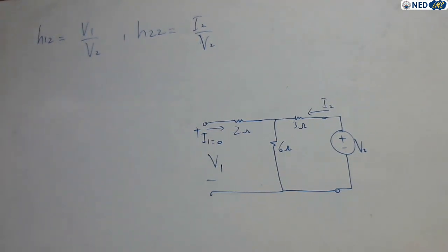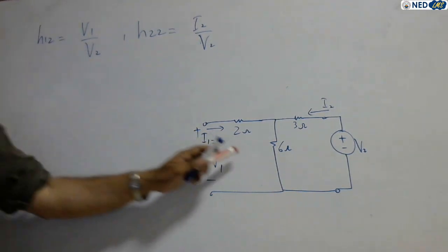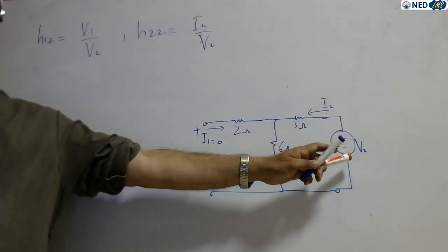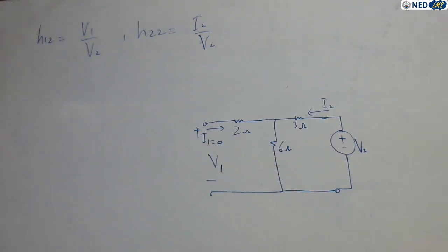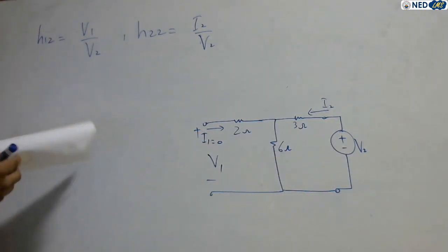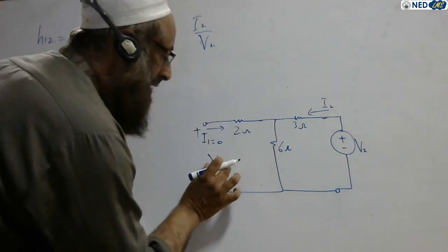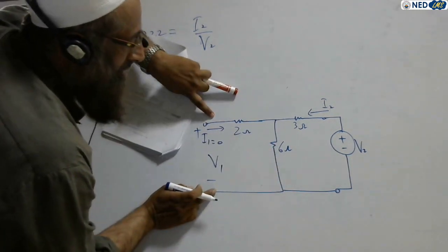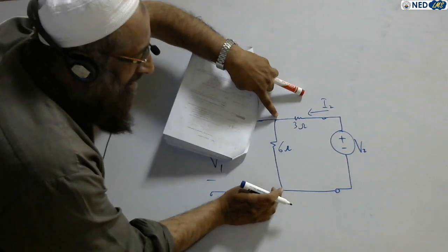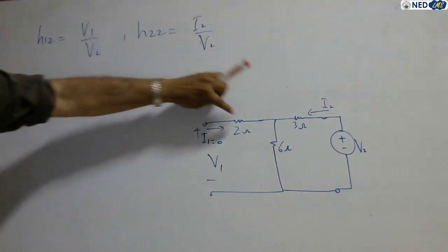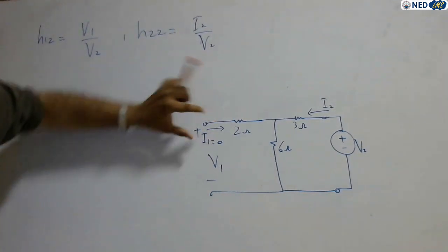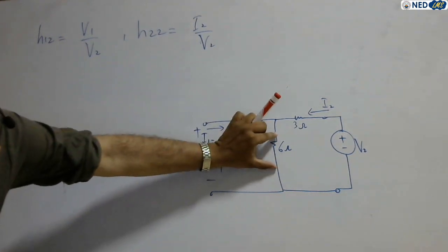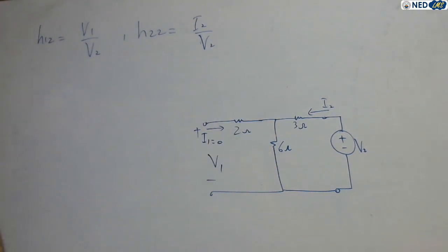Admittance. So for this, consider the circuit where the output terminal is connected with the voltage source and the input remains open circuit. So how do we calculate V1? See, what is this voltage V1? This voltage is the same as this voltage. Why? Because there is no current, so no voltage drop. So the 6 ohm voltage appears directly across V1.